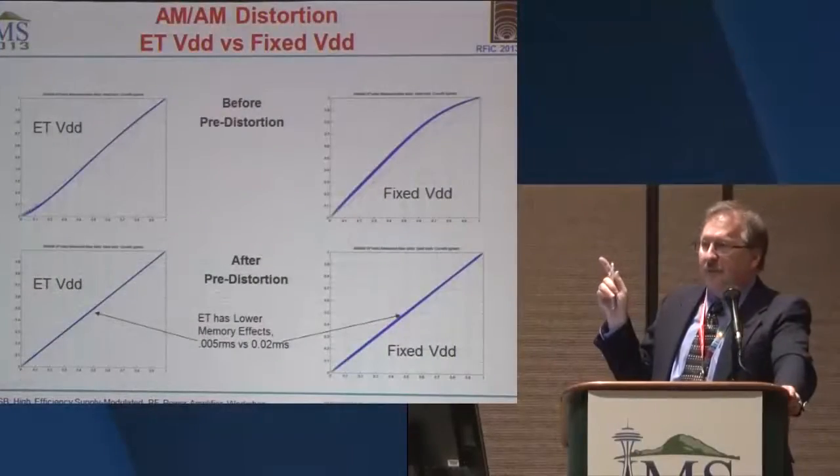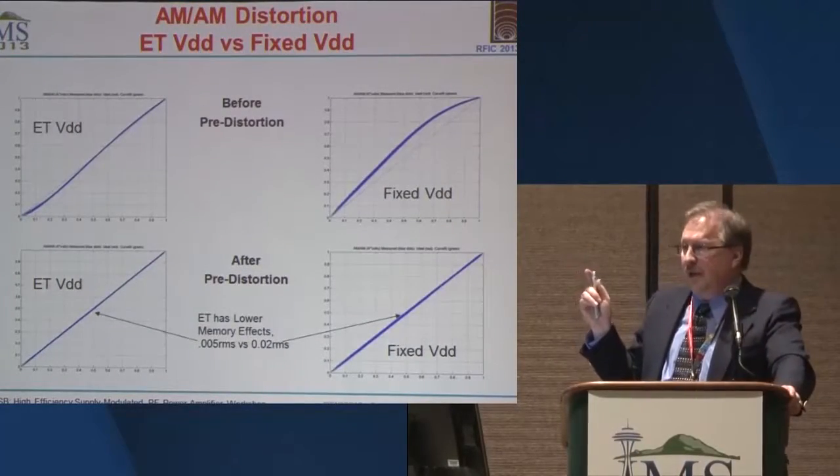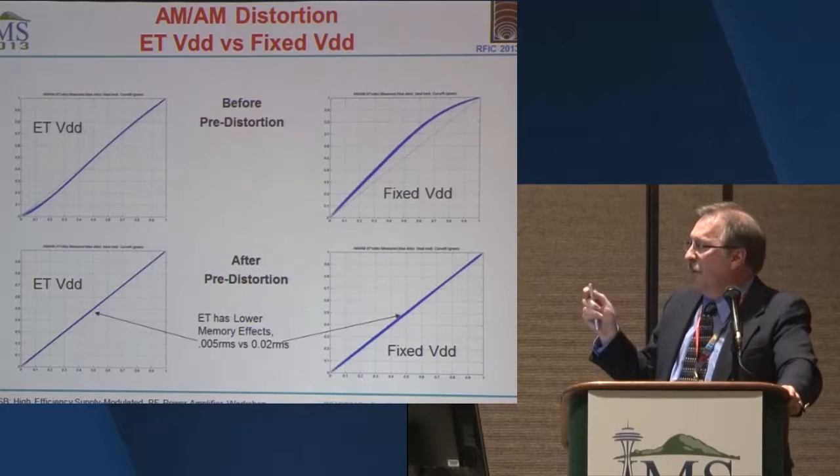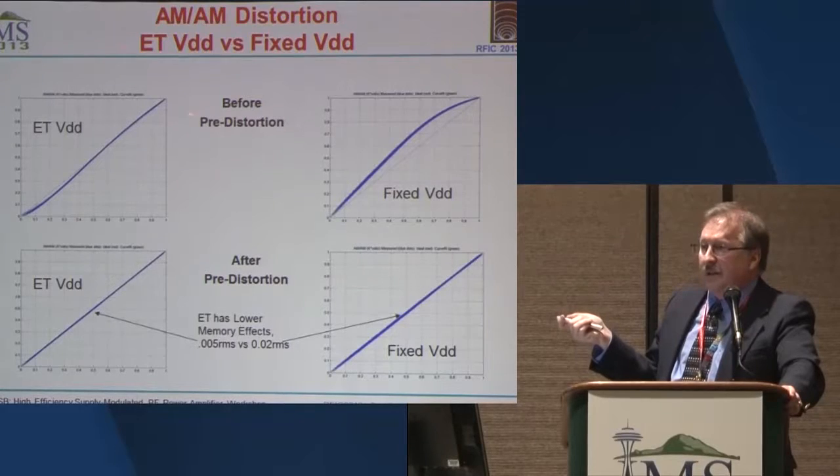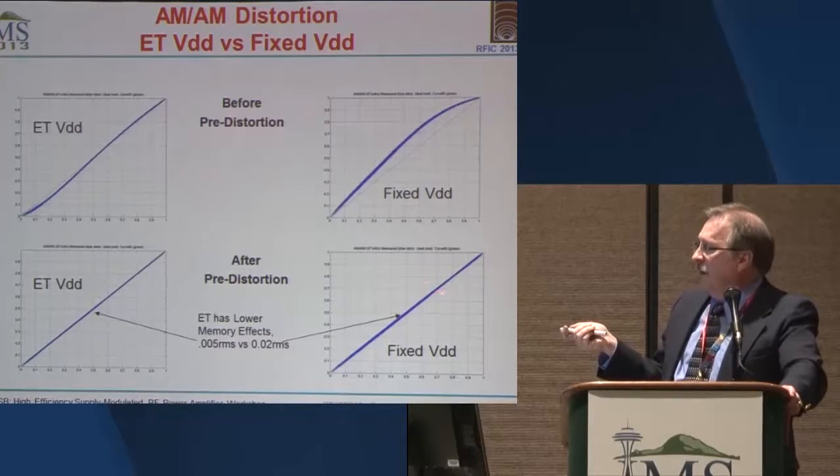The other thing I wanted to point out on this slide: this happens to be a pretty narrow bandwidth signal, and it's using a very high fidelity envelope amplifier. This is the same device, with more capacitors tacked on the VDD supply line. You'll notice that the RMS error between these two is reduced significantly.